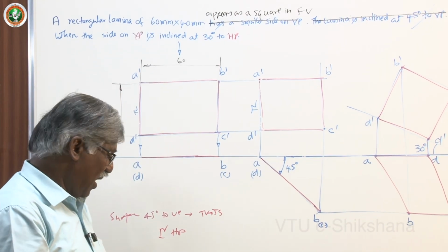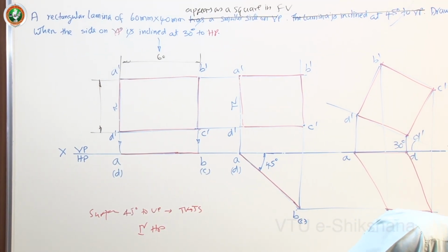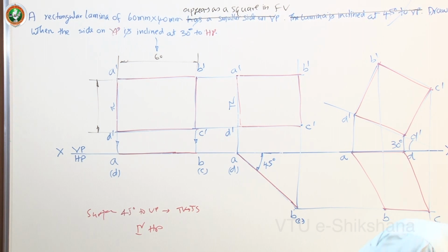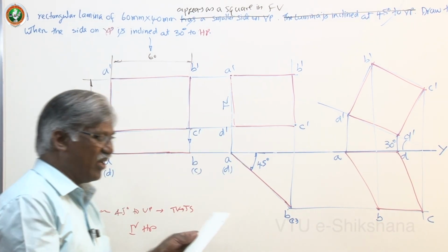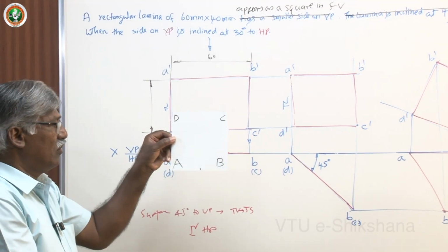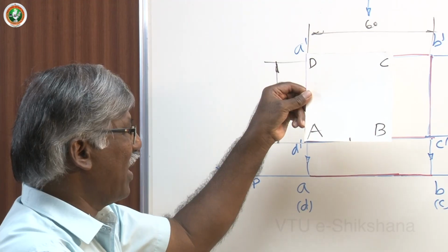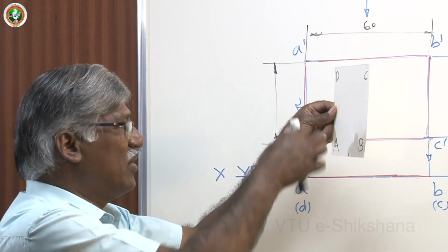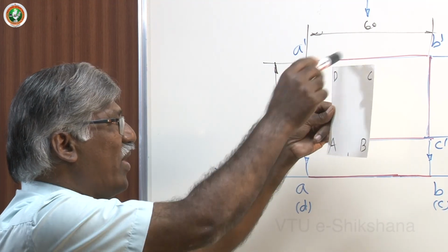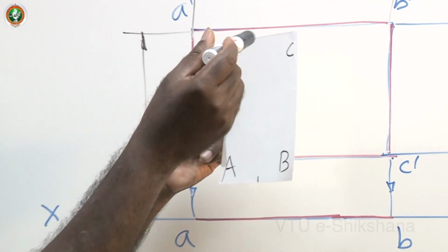At the same time, I will give one more idea about what is called square, and then it appears as rectangle. Same type, same concept. The square is on VP, say, or away from VP, parallel to it. Then rotate, you will get rectangle. So this is constant, say 40 mm square, this is 40 mm. This may become 15 or 20 or whatever.